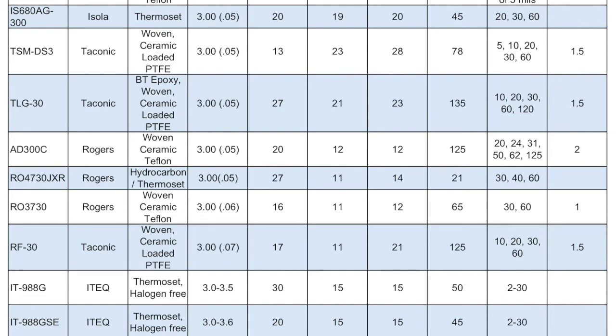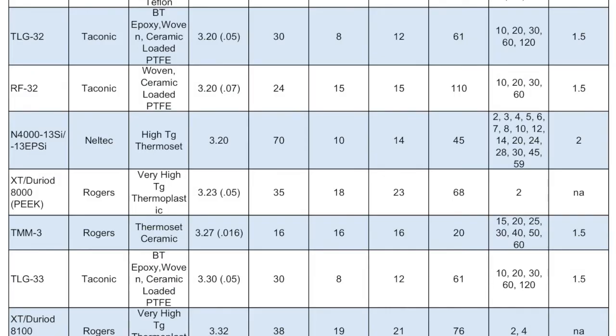Number one being cost, and usually there's some compromises or can be in electrical performance. Again, that's a landscape that's changing a little bit, and we see some of these thermosetting materials are now being utilized widespread in areas that have traditionally only been the domain of ultra low loss, ultra high Teflon content materials. Okay, that makes a lot of sense.